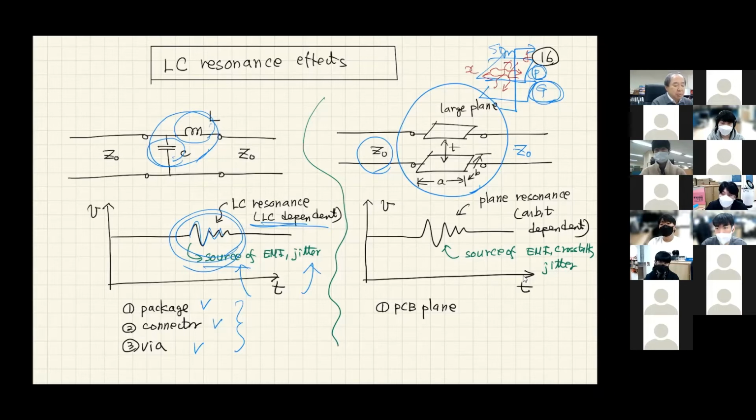In transmission line case, we only consider incident and reflections in the Z direction, but in the power and ground planes in the PCB, the difficulty is that you have X direction incident and reflections and Y direction incident and reflections, and all these ends are open terminations. And because power and ground cannot be connected together, if you connect power and ground, it is gonna become a short circuit.